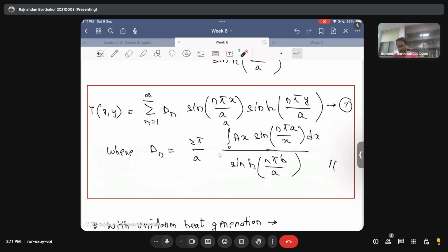Precisely, n equal to 1 is the most powerful mode, and it typically drives the solution. So you cannot discard n equal to 1 and start from n equal to 10 up to 20, because then your solution will not be mimicked. As you increase n, the modes become less powerful, and depending upon your computational power, you can truncate n at that point. Typically you can continue up to n equal to 5 to 6, and this should give a fairly good result for the temperature profile.